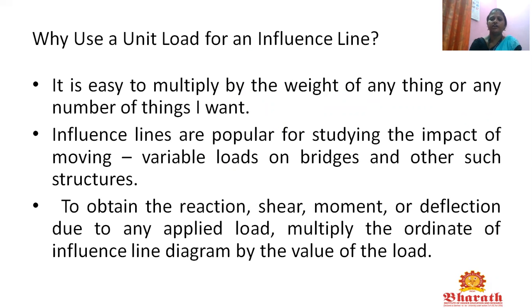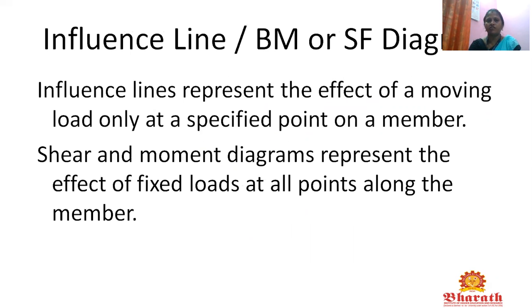To obtain the shear, reaction, moment or deflection due to any applied load, we multiply the ordinate of the influence line diagram by the value of the load. Influence line versus bending moment diagram or shear force diagram: the influence line represents the effect of moving loads only at the specified point on the member, while shear force and bending moment diagrams represent the effect of fixed load at all points along the member.